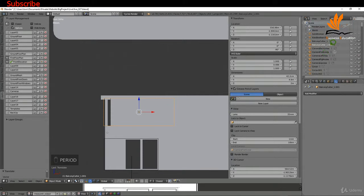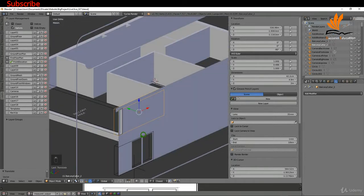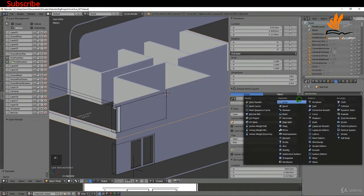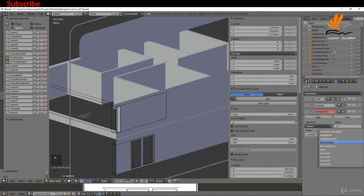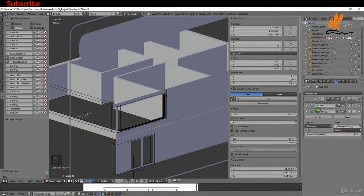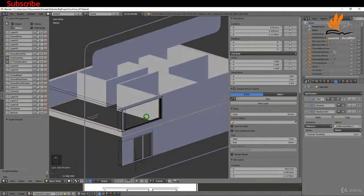If I press the period key over here, I'm just going to change this to _2. Press enter. Press and hold the middle mouse button just to come around. I'm going to select the wall again, and I'm going to add another Boolean modifier, and this time it's going to be balcony cutter 2. I'm going to set this to difference. Okay, and that looks pretty good.